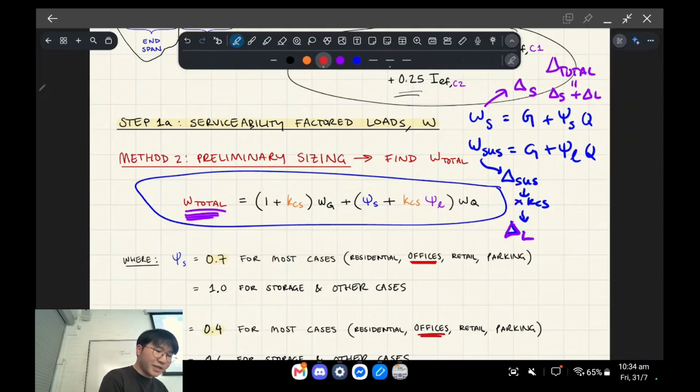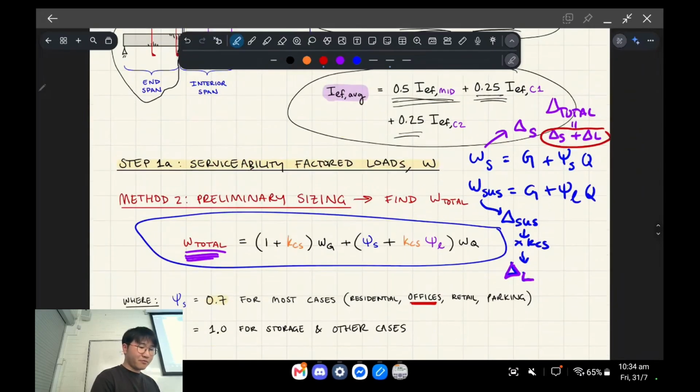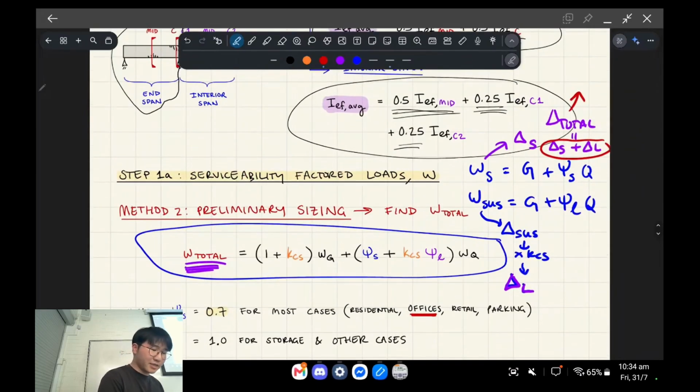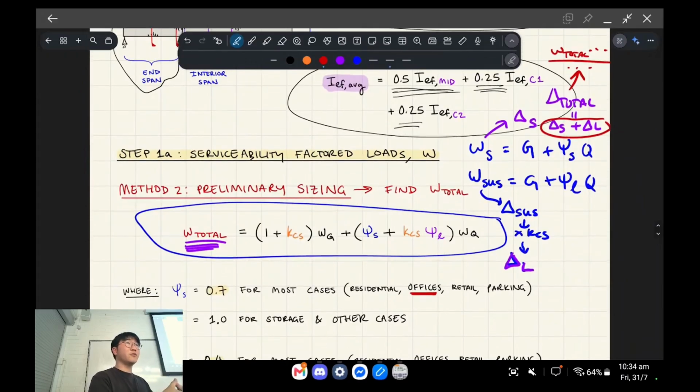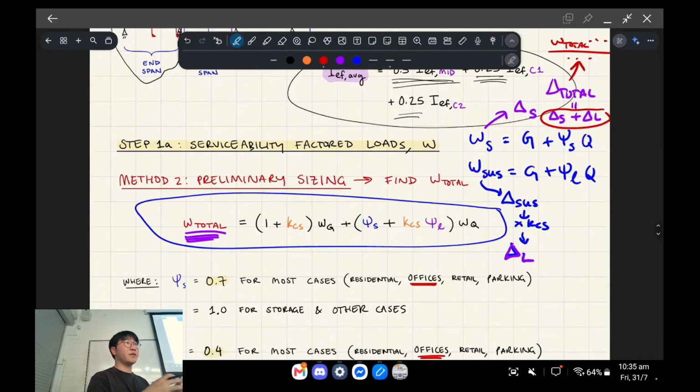Right? So what we're saying is, let's make up an imaginary load, which basically tells us the deflection if we were to plug it into that big deflection formula, and this load would represent all the creeping effects, etc. This is not a real load. This is a load which gives you the equivalent answer of if you just did elastic analysis for the deflection.